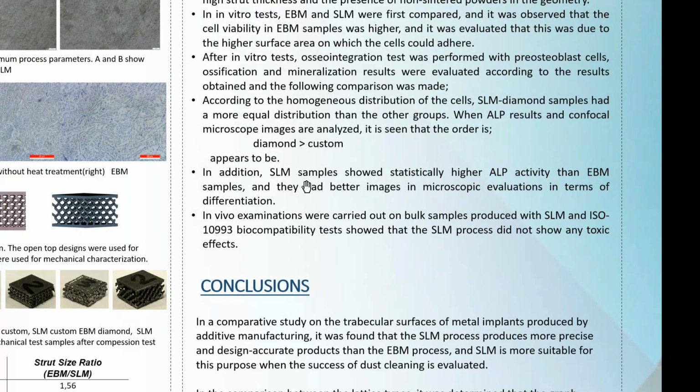Also, SLM samples show statistically higher mineralization activity than the EBM samples. We also conducted in vivo examinations according to the ISO biocompatibility standards, and the SLM process did not show any toxic effects.